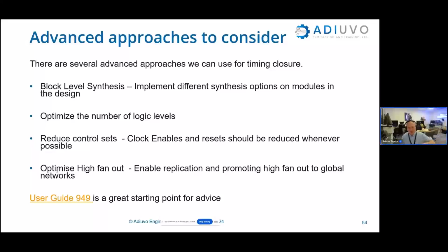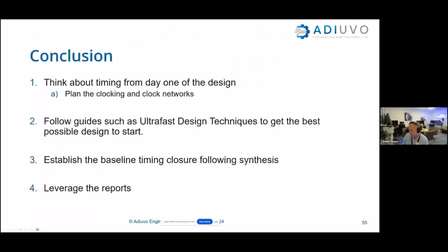And again, we can look at reducing control sets and optimizing high fan-out networks, which we looked at in our developing RTL for timing closure webinar a couple of weeks ago, and it's also on our website. User Guide 949 is a great place to get started with this.